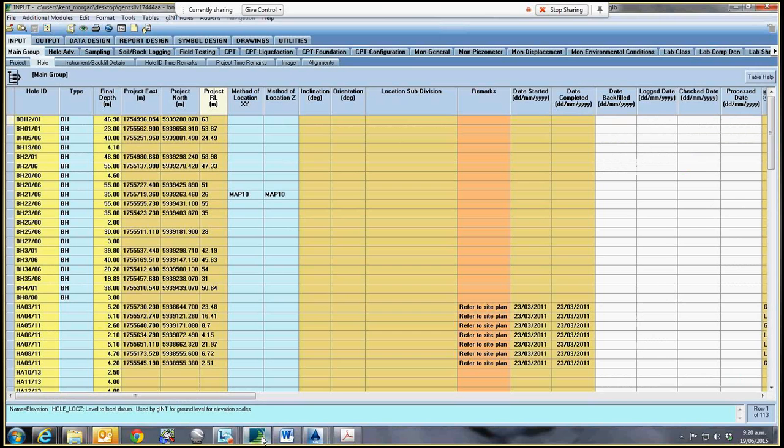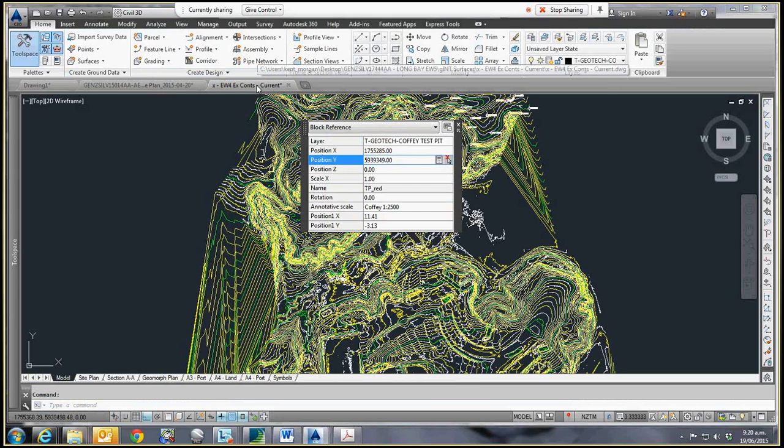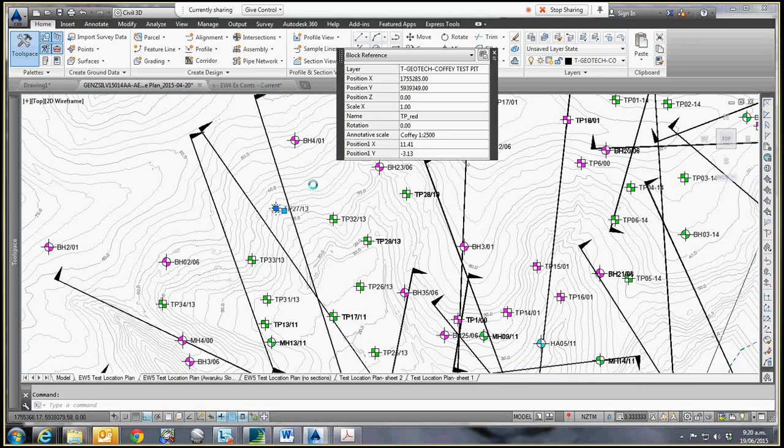It's very, very important that your coordinates for your boreholes match your cross-section. So in the lower left-hand corner, it says 175, 59382. And I should be able to go over here, and it should be relatively similar, 175, 59382. That tells me that it's in New Zealand Transverse Mercator projection.